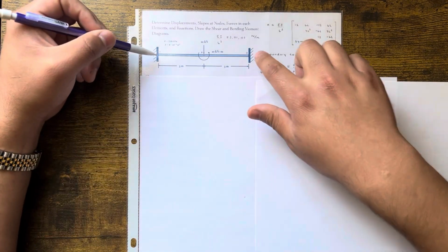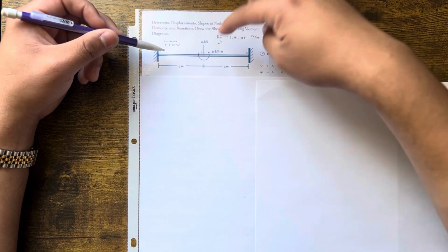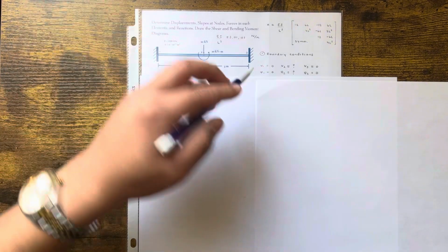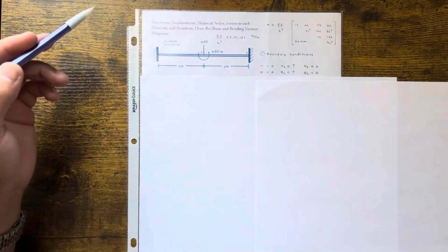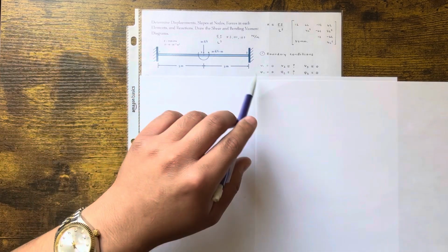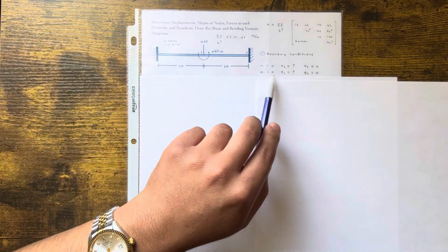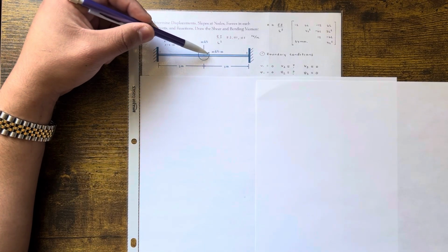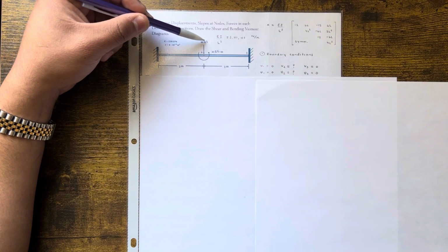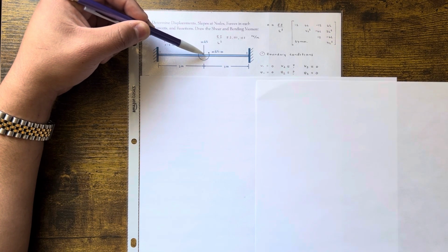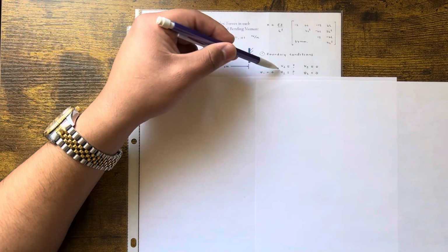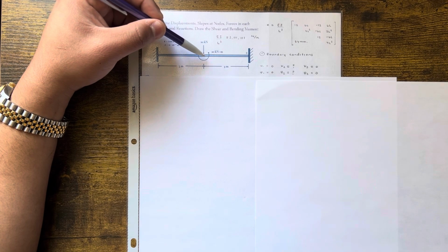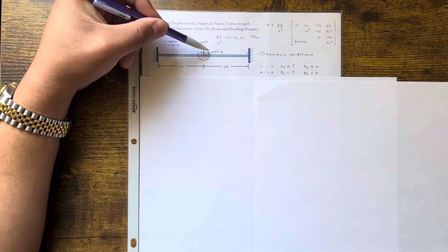So we know at node 1 and 3, they're both fixed. So no matter how much force you put along the beam anywhere on any of the 2 beams, you're not moving that thing, right? So V1 and V3 are 0. Because they're fixed, your angle of rotation at these 2 nodes is also going to be 0, okay? So if you apply a force going down and then a rotation at node 2, you're going to displace some number and you're also going to rotate some number, okay? So V2 and phi 2, we don't know. Even if you didn't have a moment, you still would have some rotation, right? Your moment would just be 0 in that case.